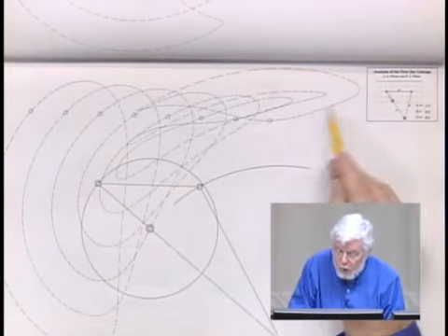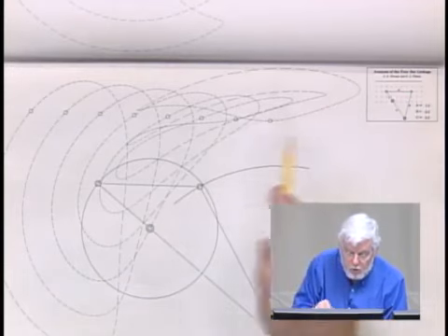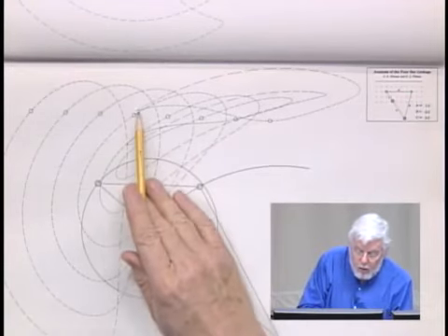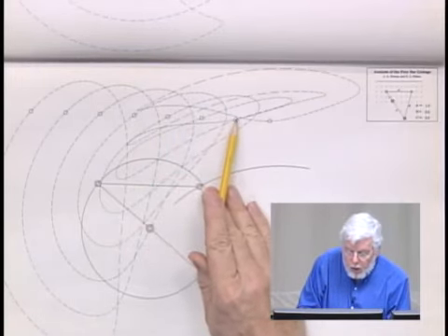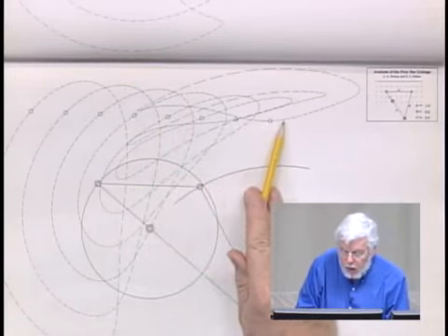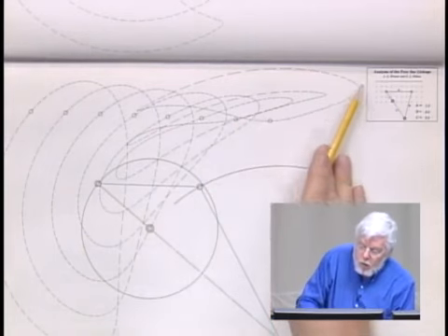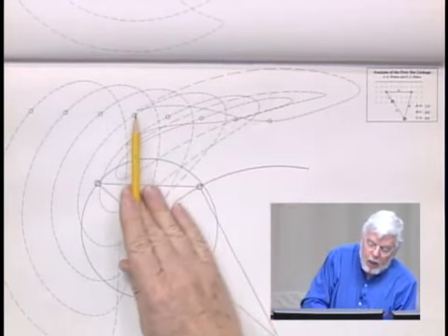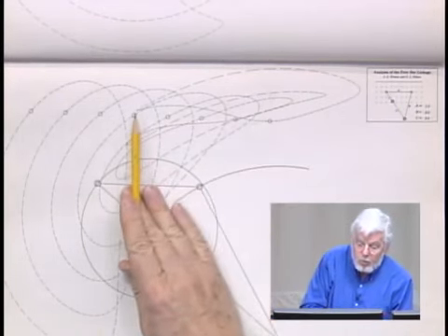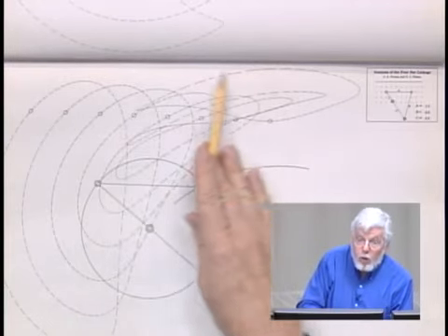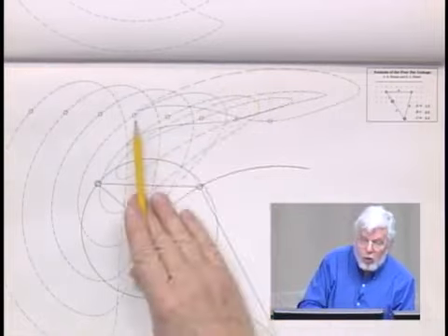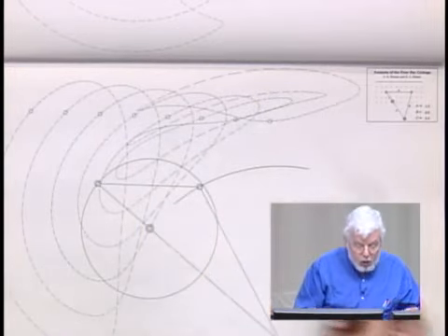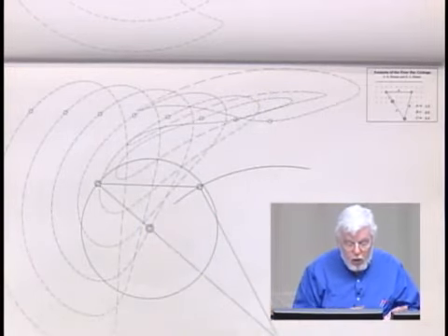And I didn't make that point when I first chose this curve. Coming down here, I'm moving at relatively constant velocity. It's speeding up a little bit there, and then it slows down again as it comes around the corner, and then it goes like the dickens back to my cusp. This would be called a quick return mechanism, if I consider this to be the forward motion and this to be the return. So by just looking at these curves, I can see the relative quick return nature of them.